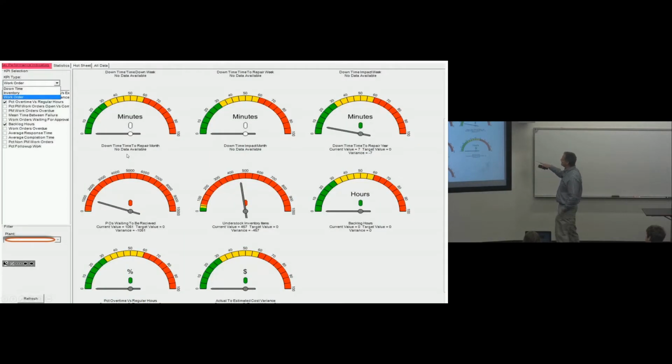And this is what I spoke of, the dashboard. There's many software programs that tell you how you're doing. So what's my OEE, mean time to repair, mean time between failures? How am I doing relative to completing all the PMs? A larger organization, they may have 150 PMs that are required almost daily across the whole organization. Where are we on those? We're 90-some%. Well, what are we missing? 5%. What are the ones we're missing? And why are we missing those? We can drive that compliance to the PM schedule.